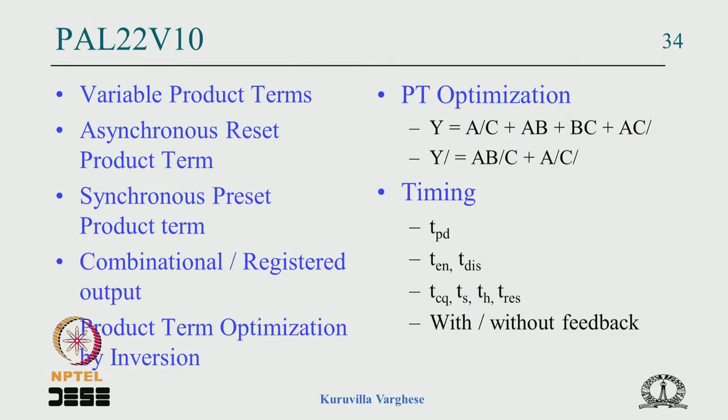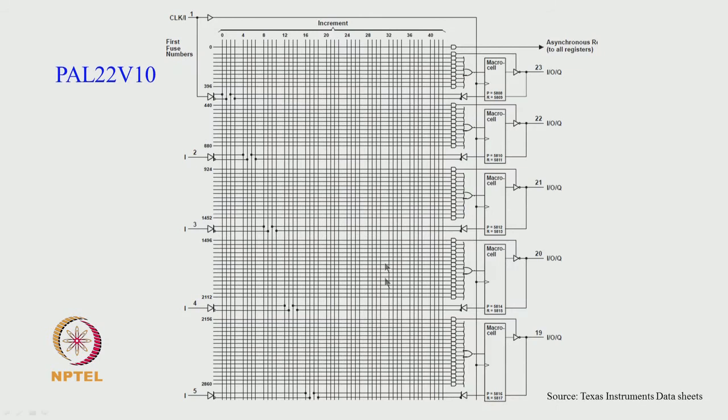But if you think of it as cascaded 2-input XOR gates, say the first 2 inputs come here into 1 XOR gate, that means 2 product terms are formed, and that XOR gate output is cascaded to the next 2-input XOR gate and so on, like a chain in the 8 sections.